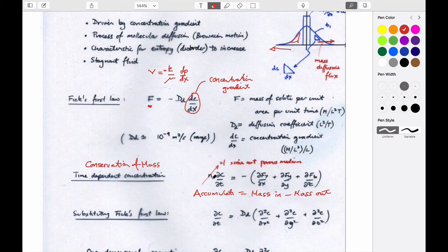And this says that the change in concentration in this bucket, this differential cube, occurs at a rate which is the difference between the stuff coming in and going out. If it comes in at the same rate it goes out, there's no accumulation. If it comes in faster than it goes out, then there's a net accumulation. And so this is just a statement of that. And so Fick's law, which says how quickly mass travels driven by a gradient, you could imagine plugging into this to represent gradients in the x direction, the y direction, the z direction. It's not particularly important.